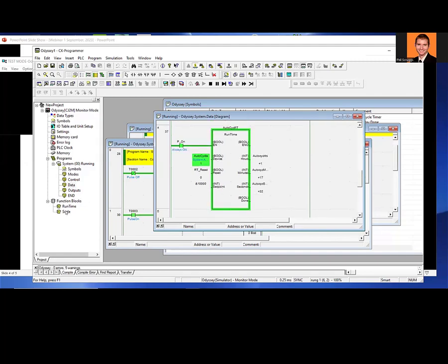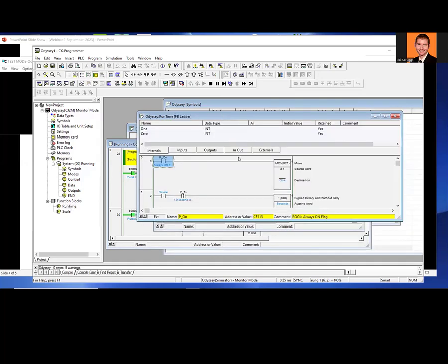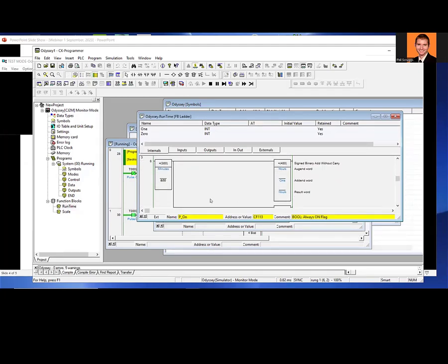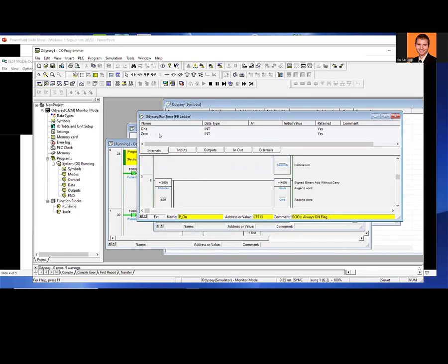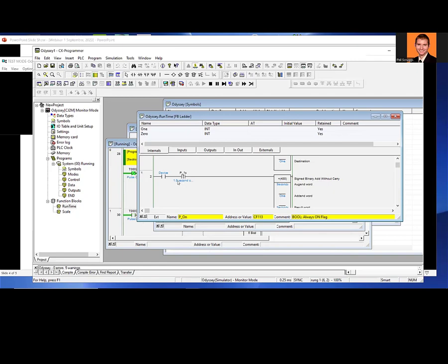You can open up these function blocks and see how they're built. Function blocks, everybody hopefully knows what those are. This is the code inside of it, and it is a reusable block that I can use over and over again. And then I would have to take it an instant at a time. This is not the way I would normally program it, but I couldn't figure out how to use the timers inside of it. So I used one of the internal 1 second pulse bits, which is this device with a 1 second one shot. And then use that to count